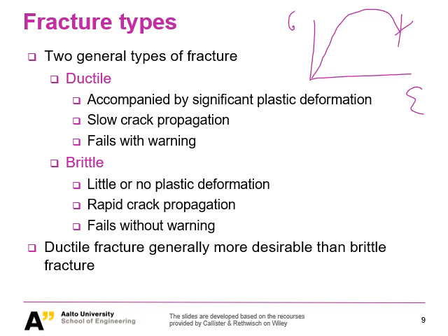But what you can also easily use as a warning is, for example, the tensile strength as the crack initiation warning, and even for some cases people use the yield strength, right? So as long as you see anything develop to its maximum force or maximum engineering strength, you would say, okay, at a certain point we might see a ductile fracture later on, right? So these are the three important features of ductile fracture.